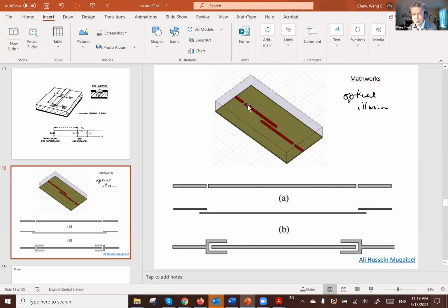But essentially, what you have is a microstrip resonator here. You have another microstrip resonator here, and you can concatenate them to make a broadband filter. Another way of seeing it is that you might have a concatenation of resonators using microstrip lines, and then you use capacitive coupling between them to couple the energy from one section to another.